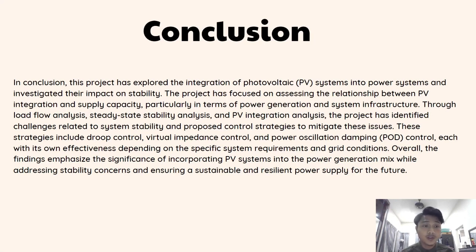Through load flow analysis, steady state stability analysis, and PV integration analysis, the project has identified challenges related to system stability and proposed control strategies to mitigate this issue. These strategies include droop control, virtual impedance control, and power oscillation damping, which is POD control, each with its own effectiveness depending on the specific system requirements and grid condition.